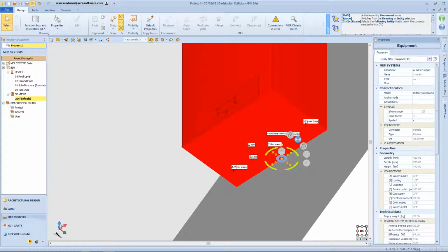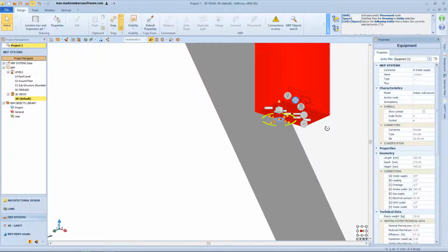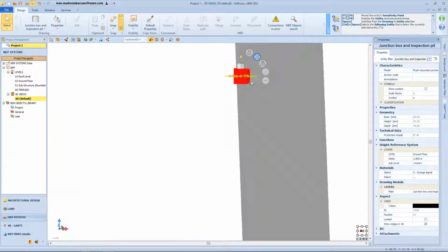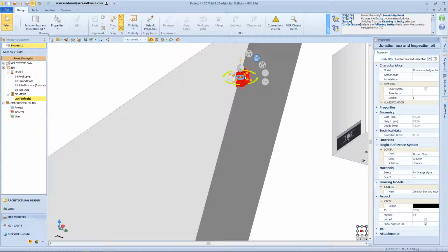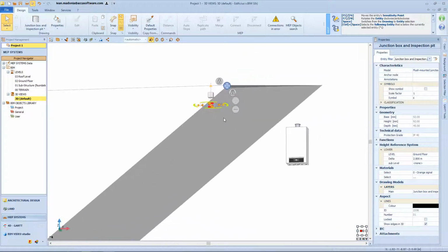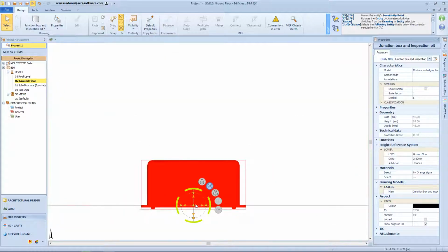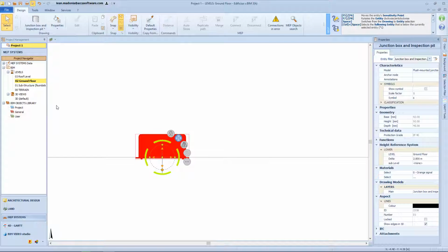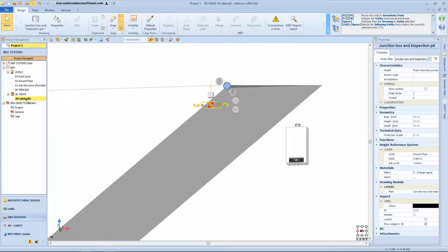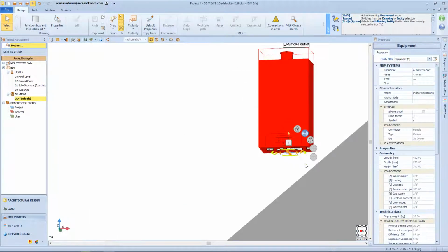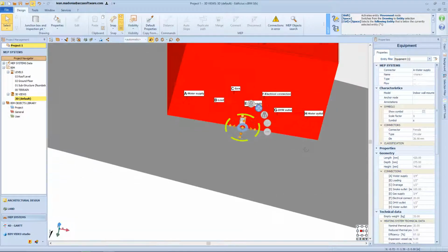Connections can be managed both on levels and by working in the 3D view. However, the display on the layer will be limited to only the connectors, if any, visible from that observation point. On the contrary, in the three-dimensional view it's possible to orbit around the object and thus recognize any connectors at each point. Let's consider the implementation of connections of an MEP object in the 3D view.